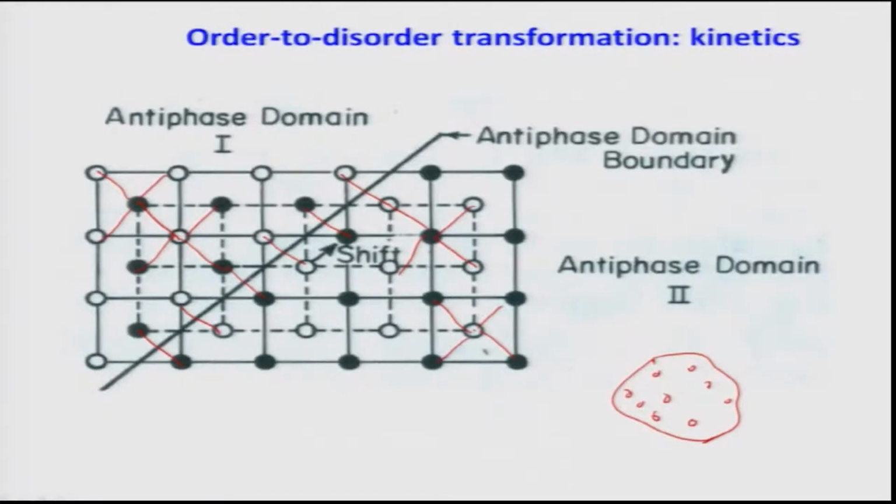How can we do that? You can very easily see this copper-gold atom which is sitting here should have been a copper atom, then the bonding would have been opposite, or this copper atom should have been a gold atom, then this bonding would have been copper. That has not happened. So therefore we can talk about atomic displacement. Crystallographically the atomic displacement will be a/2 [1 bar 1 1], and this happens mostly on {110} planes. That can be seen from the crystal structure. The {110} planes are why the displacement is happening.